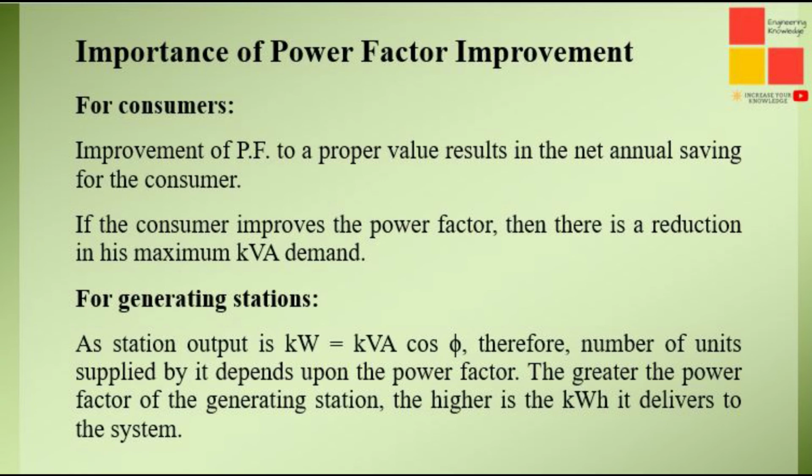The importance of power factor improvement: from the consumer's point of view, improvement of power factor to a proper value results in net annual saving for the consumer. If the consumer improves the power factor, then there is a reduction in his maximum kVA demand. And on the generating station side, as station output in kW is equal to kVA cos phi, the number of units supplied by it depends upon the power factor. The greater the power factor of the generating station, the higher the kilowatt-hours it delivers to the system.